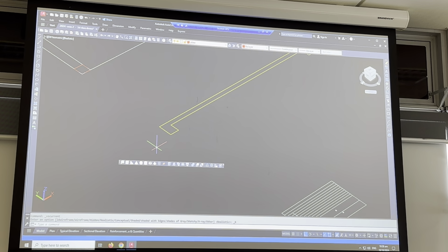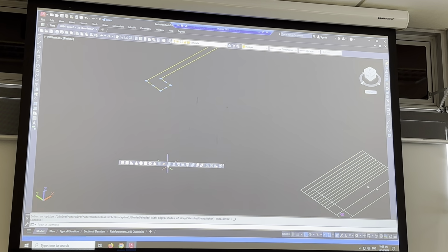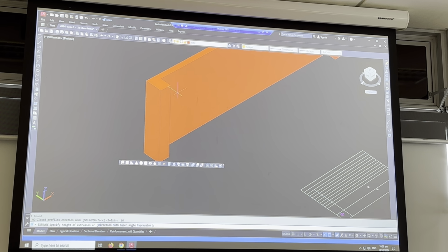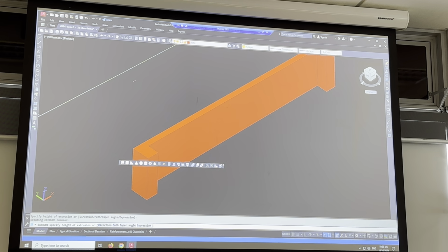Yeah. Okay, so I'm going to grab this P line here, and I'm going to go to extrude. Look what's happening. All sorts is happening. But even your rebar is flat. Yep. Now, what I'm going to do is I'll try to extrude it upways, but it may go the other way. And I'm going to type in, oh, I forgot, 6.8 is it? 6,800.